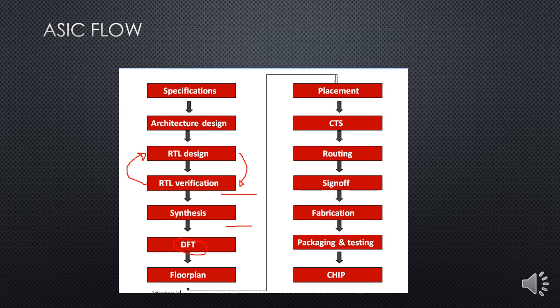So now the fabrication engineer or the process engineer will look into what has gone wrong, and he'll find out, and only then will the fabrication steps resume. So that means DFT plays a prominent role. Once the chip is fabricated, which ones need to be shipped to the customer and which shouldn't be will be decided here. Thanks to the DFT engineer, who adds some design logic to enable this process. So that is the functionality of the DFT engineer.